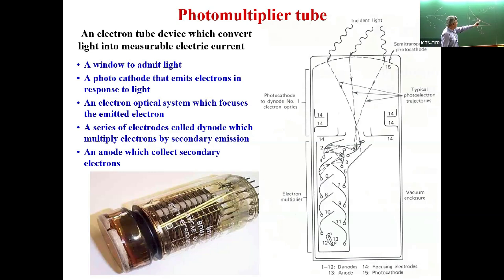When the energy of the photon is increased, my absorption coefficient is increased. So when energy is more, more photons are absorbed in the glass and the quantum efficiency decreases. And when the energy is reduced, the absorption in the photocathode also reduces, so again the quantum efficiency is reduced. So this is the optimum where I have a maximum. When the wavelength is more or less, my absorption in this photocathode material will reduce.